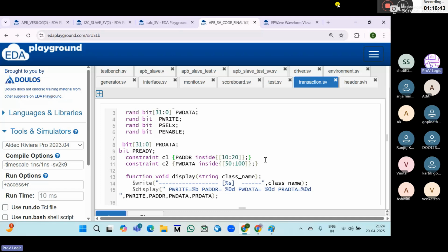So what will be the test cases available for APB? First, we need to do basic write. After, we need to do read. Then we need to check write reads. And these are the directed ones. So we can do random read write combinations, like one read after write. And we can conclude this with what the design supports. We can verify wait scenarios and no wait scenarios that you explained in the session, right?